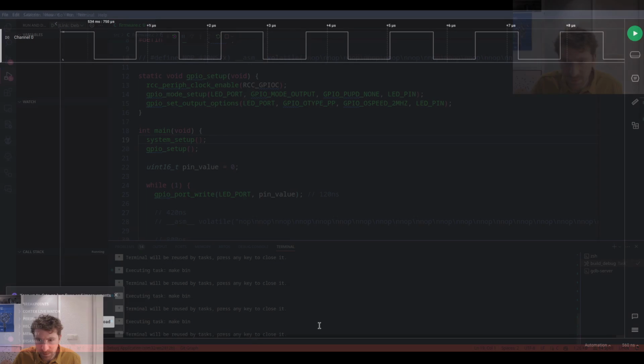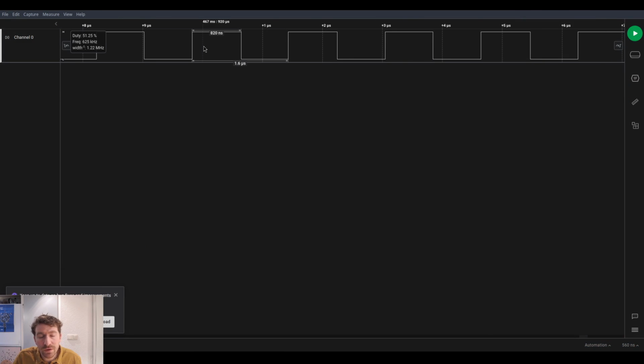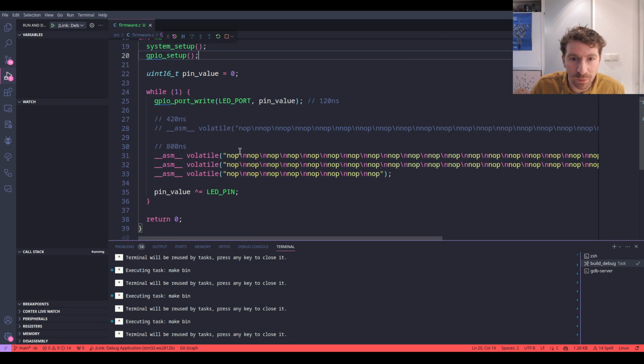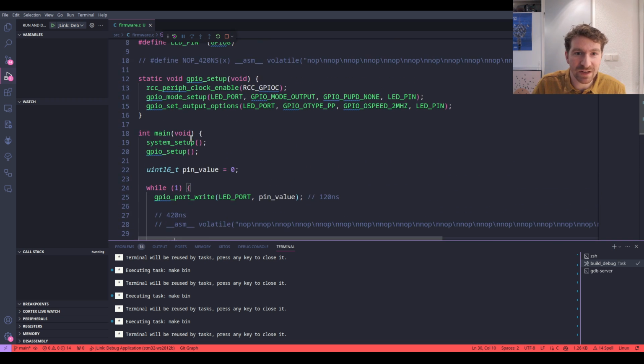Alright, we're running. We switch back to logic, we run. 820 nanoseconds, 820, 800. This is perfect, alright? We're going with that. So that gives us this number of no-ops for an 800 nanosecond or an 820, and this gives us 420. I'm really happy with that. So that means that we can now generate the right timing, the right number of on-off time in order to start thinking about generating an actual 1 or a 0.